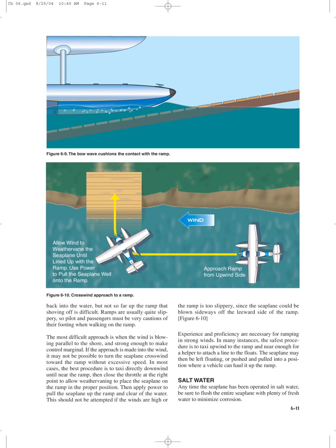Anytime the seaplane has been operated in salt water, be sure to flush the entire seaplane with plenty of fresh water to minimize corrosion.